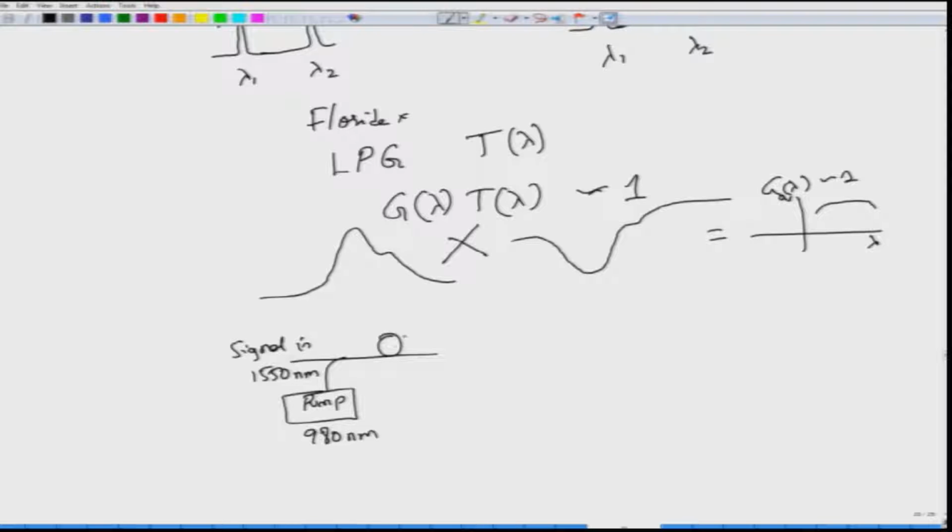and this would go into the fiber. So this is your erbium doped fiber, but not the entire pump would be utilized. Some part of the pump might still be available, so that forms the residual pump, and after this you normally put in an isolator. If you want to make an equalizer, then you also put in a long period grating at this point, and then you also put one more erbium doped fiber just to symmetrize the whole thing, but this is essentially what you are going to see in a commercial erbium doped fiber amplifier for broadband application.